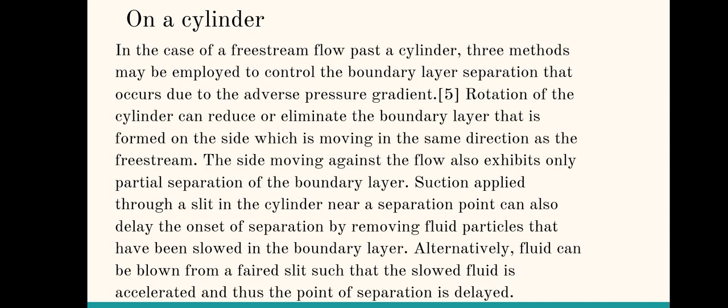Suction applied through a slit in the cylinder near a separation point can also delay the onset of separation by removing fluid particles that have been slowed in the boundary layer. Alternatively, fluid can be blown from a slit such that the slowed fluid is accelerated and thus the point of separation is delayed.